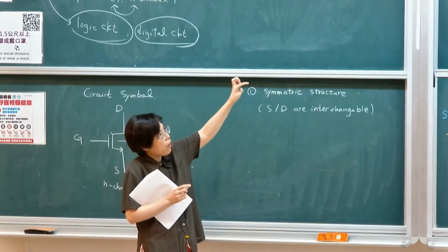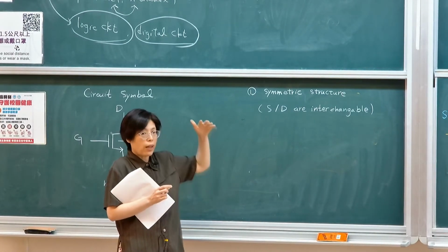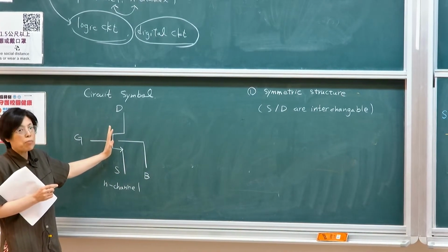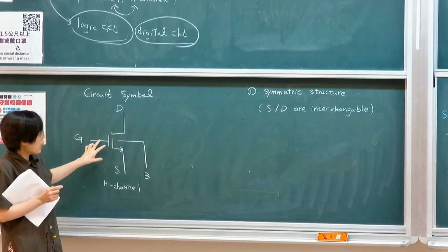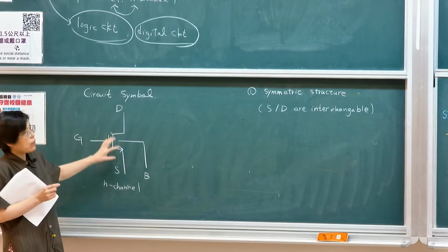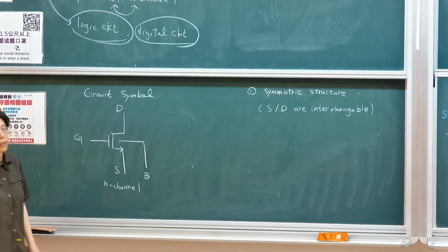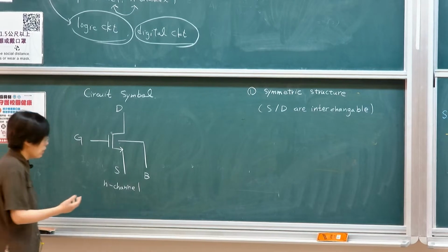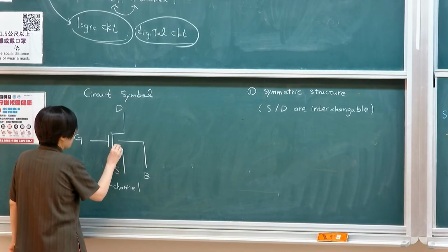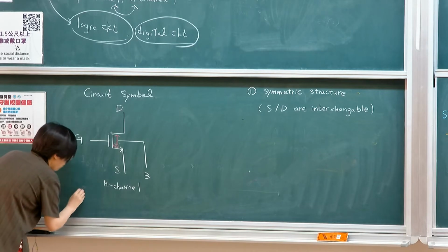If you look at metal oxide semiconductor, if you consider the semiconductor as an electrode, then you have a parallel plate capacitance. So you actually imply that there's a capacitance between the gate and the channel. Through this capacitance, I'm inducing a charge, then allowing the channel to be formed. In this case, the arrow simply refers to the direction of the current. Because it's an N channel, the channels are formed by electrons, therefore the electrons flow from source to drain. So carriers are always flowing